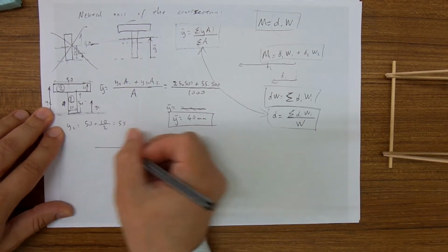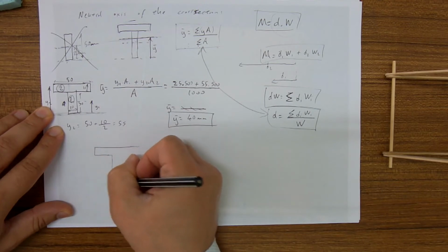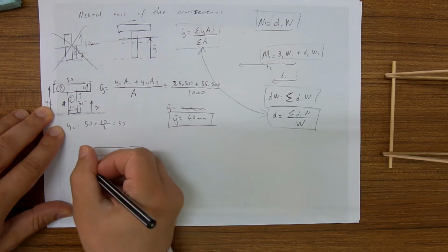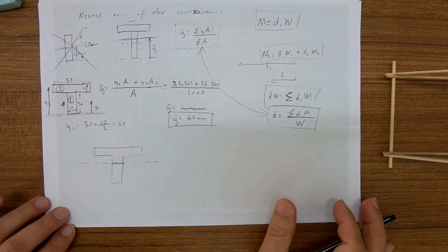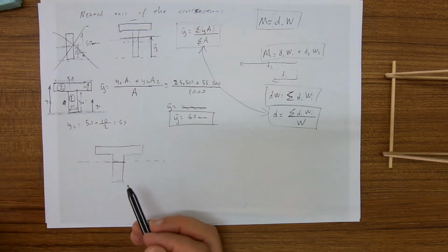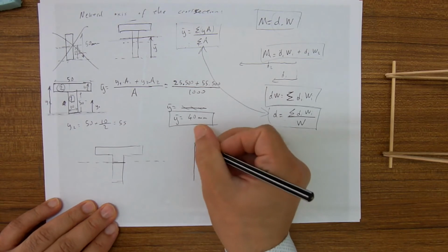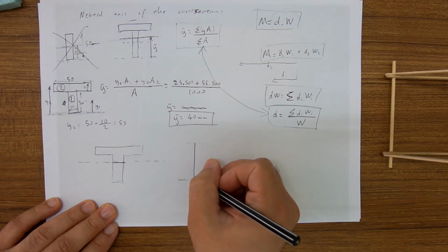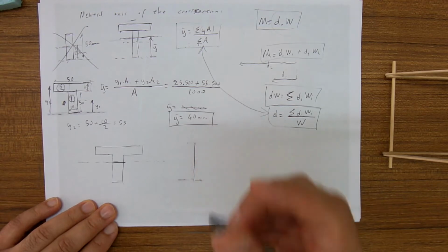So the neutral axis of this section is here. So neutral axis, what is it? We showed before, it is where the section is rotating around. You remember we showed that bending creates normal force or normal stress on the section of a beam which is under loading.